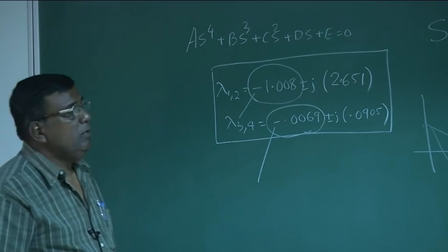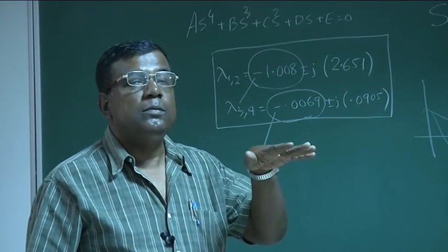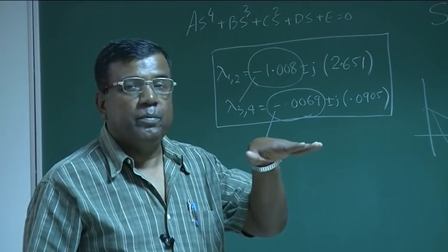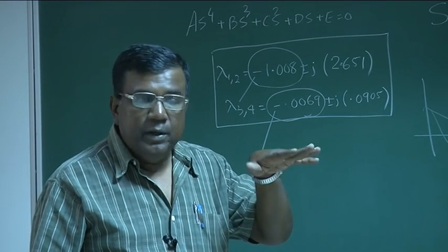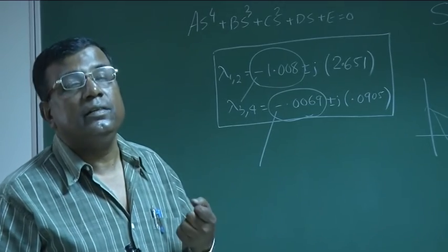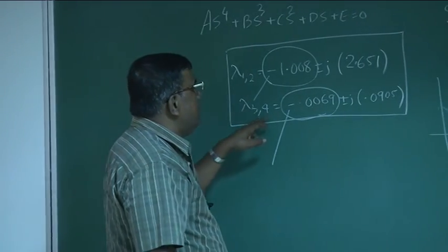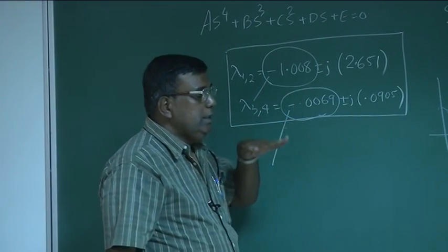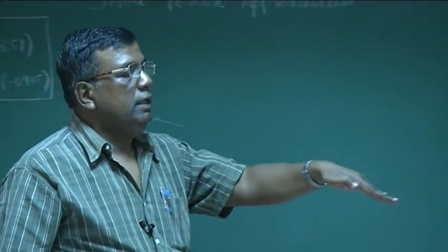Physically, when an aircraft is disturbed, it has primarily two modes of excitation. One is short period, where you disturb it and it immediately comes back. During this short period mode, there is not much change in the velocity u. The other is a long period mode, because it takes longer time, called the Phugoid mode. It oscillates like this and then comes to equilibrium.